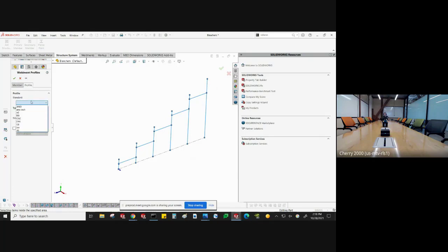I do have to warn you, if you're going straight from 18 and you have 21 and 18 loaded on your system, you may have trouble here because the 18, when you load 21 on a machine that's got 18, it's still going to use all the file locations from 18 just to make your life easier. So you're using your templates, you're using your weldment cross sections, you're using all the stuff that you were using back in 18. The trouble comes is that in versions past 18, they started giving us the ability to put configurations into these cross-sectional shapes. And this tool needs those configurations to work.